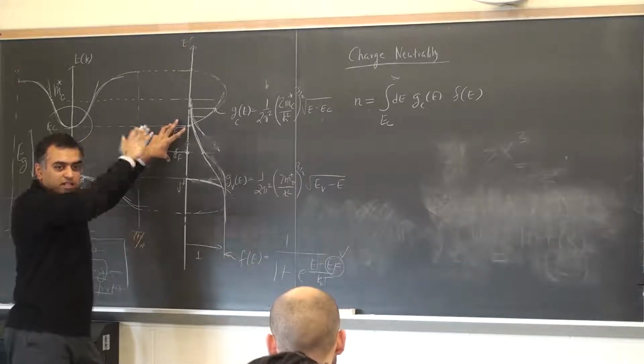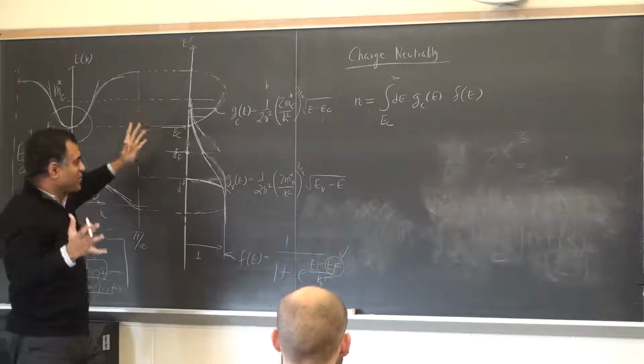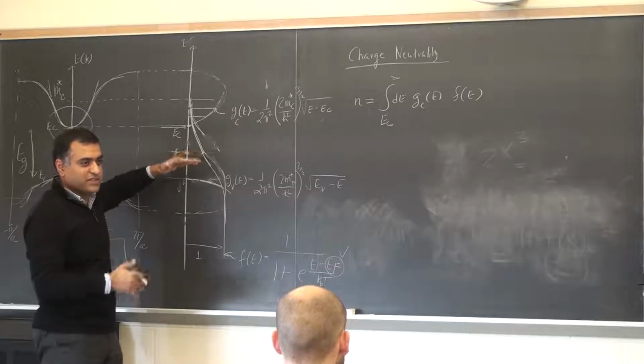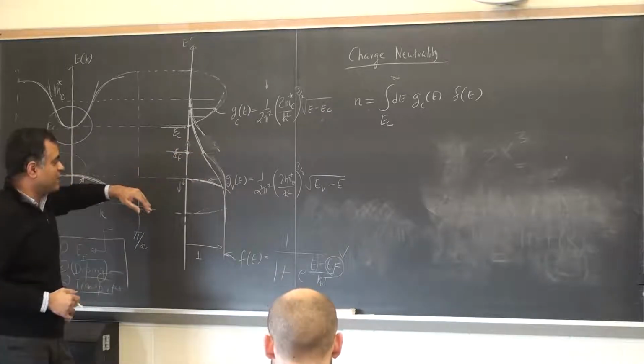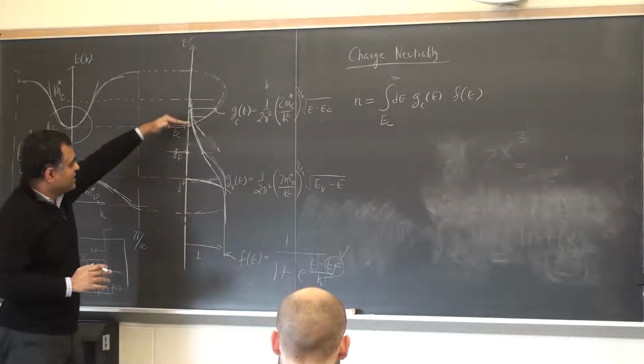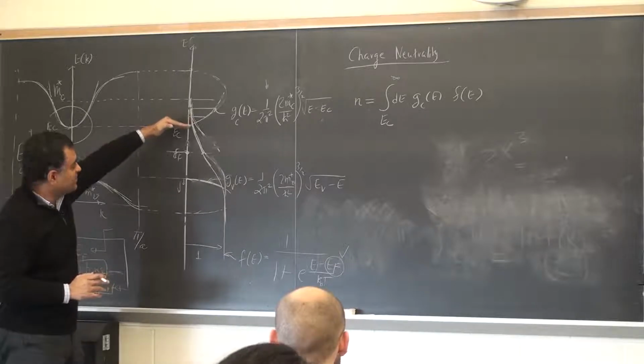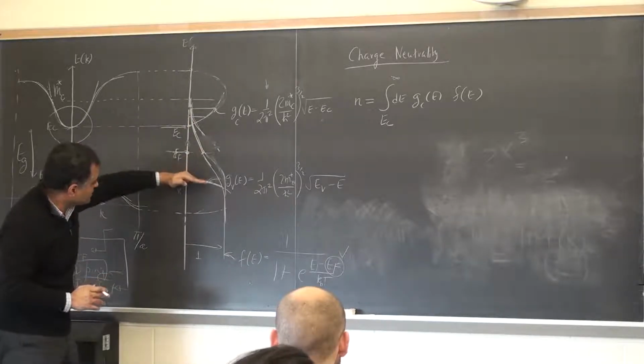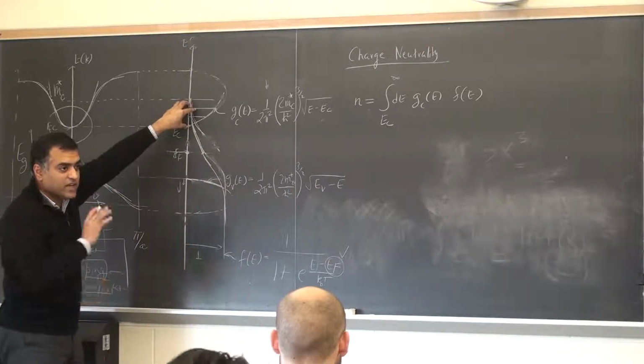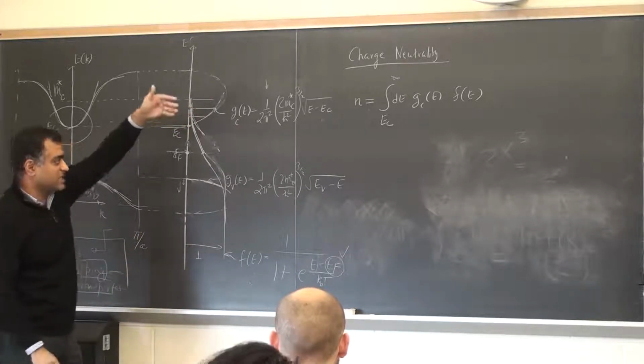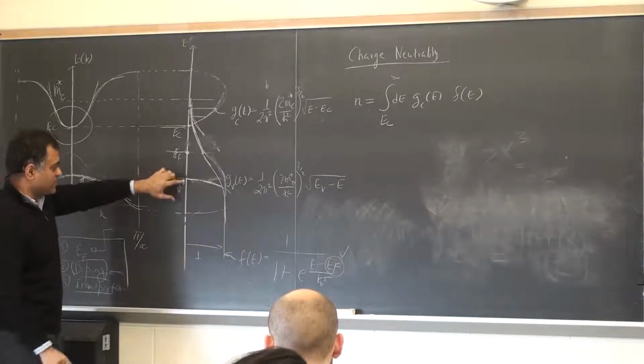So it's a carrier density. That's the most important property of a semiconductor that we make use of in a diode, in a transistor, in a rectifier, laser, all that stuff, right? So similarly, if I move the Fermi level down, I'll deplete it of carriers. I have very few carriers left here, right? And we'll see an exact exponential expression very soon.